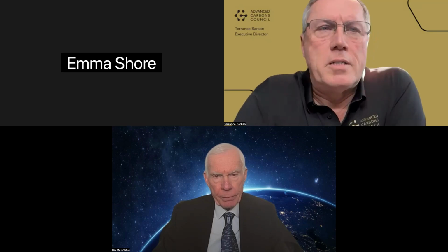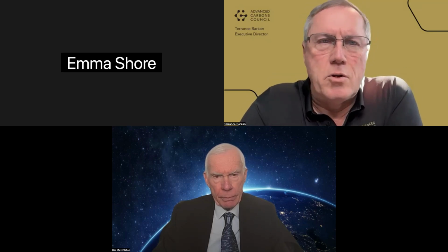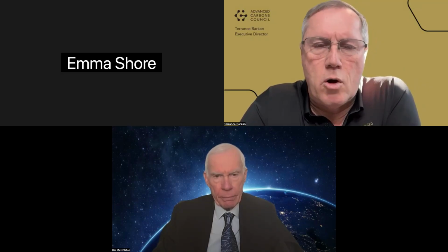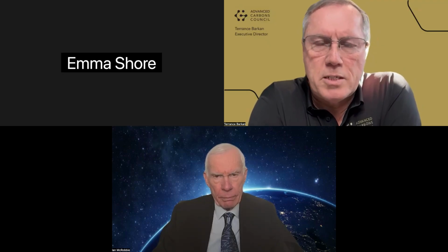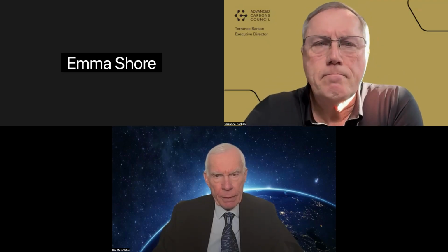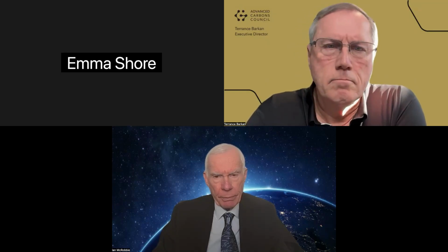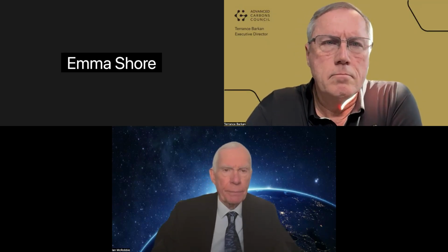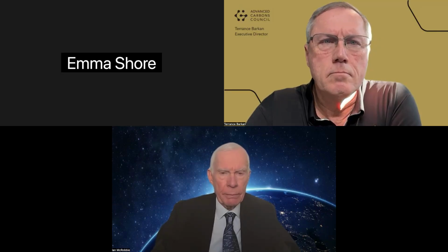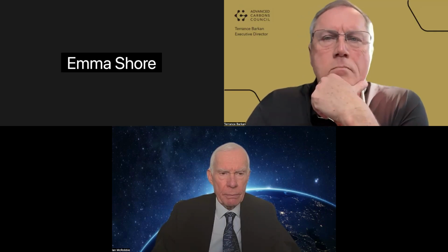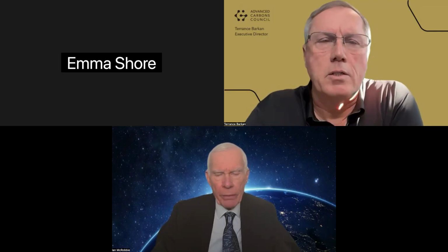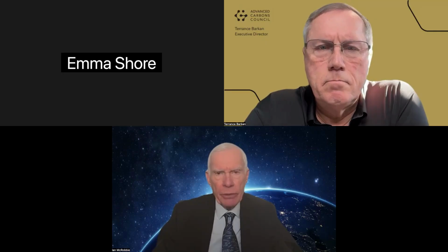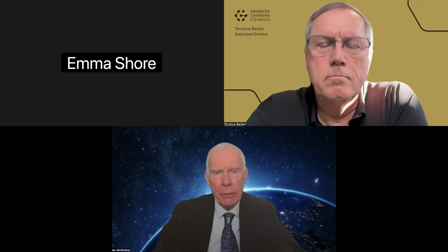One of the questions from the audience is asking, what about the quantities? How much of the catalyst is being used in relationship to the carbon-bearing feedstock? Is that something you can speak to on the ratio of catalyst required for this process? We did some work on a range of ratios of the catalyst in the carbon source, and we got quite varying results. We could use up to 9.8 weight%, which was the solubility limit of the ferrocene catalyst, but tend to get better performance at the lower level, from 1 to 4 weight%. But on the experiments that we've shown you today, we used 2% ferrocene on a weight basis with toluene.